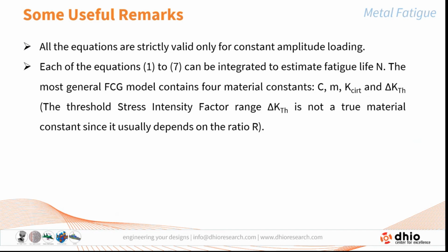So here all the equations are strictly valid only for constant amplitude loading. Now each of the equations 1 to 7 can be integrated to estimate the fatigue life of the component. And the most general is the fatigue crack growth model containing the material constants C, m, K critical and K threshold.